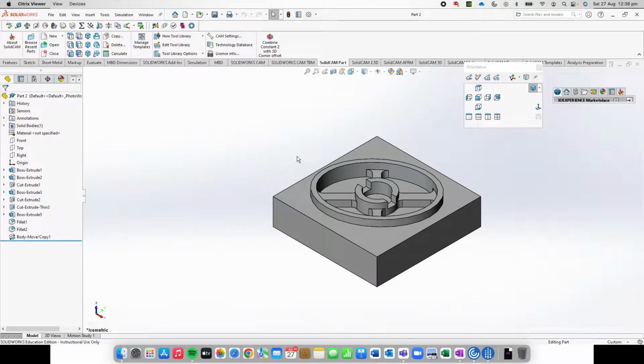Tutorial on how to do the CAM for part 1 of the assignment section 2. So, a little introduction. CAM is computer-aided manufacturing, which allows difficult geometry and parts to be machined using CNC machines. It requires code in the form of G code or M code, which is generic or specific to the machine, and it just gives the machine instructions for tool selection, geometry, feed rate, RPM, etc.